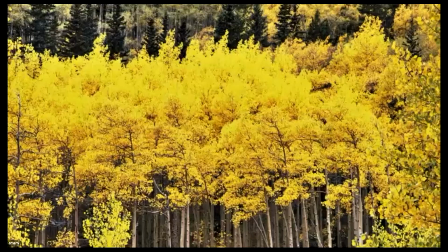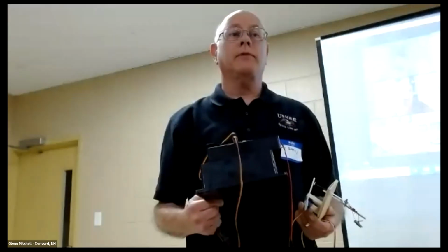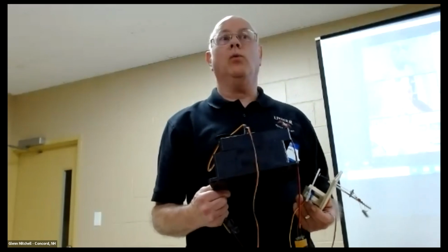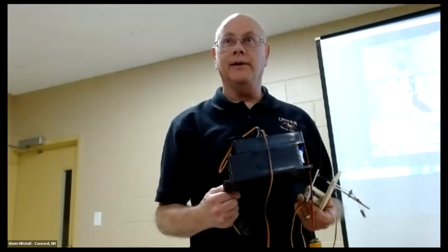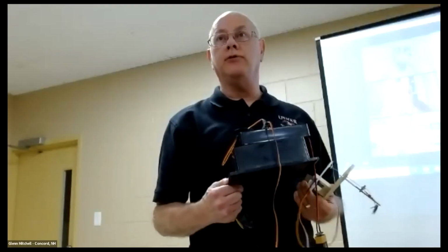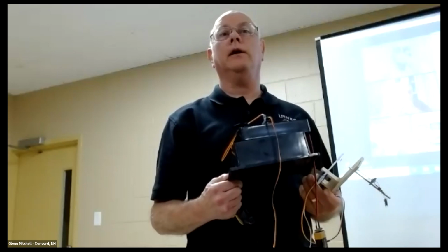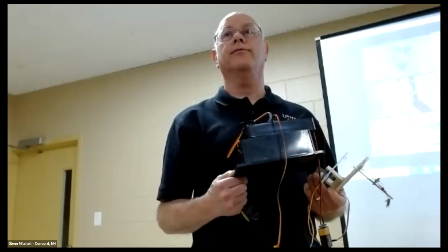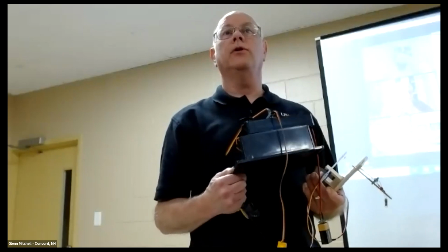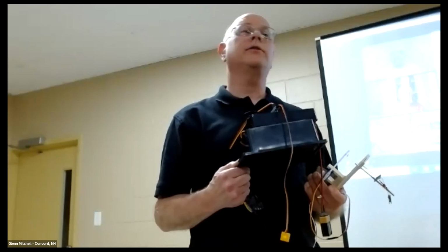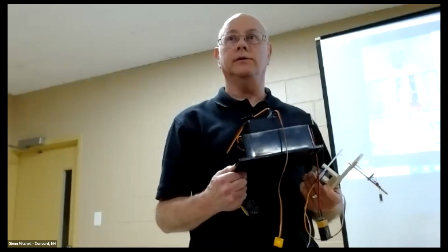When you get your Wago connectors, the connectors are easy to find on Amazon. What's hard to find, Wago makes a bracket that you can screw in. You don't need them here because these are epoxy. But for my bench work, I tried pressure sensitive tape. That didn't work real well. But Wago makes a bracket, and I got them from Newark Electronics. So you basically screw the bracket into the bench work with one screw, snap the Wago connector in, and you're good to go.